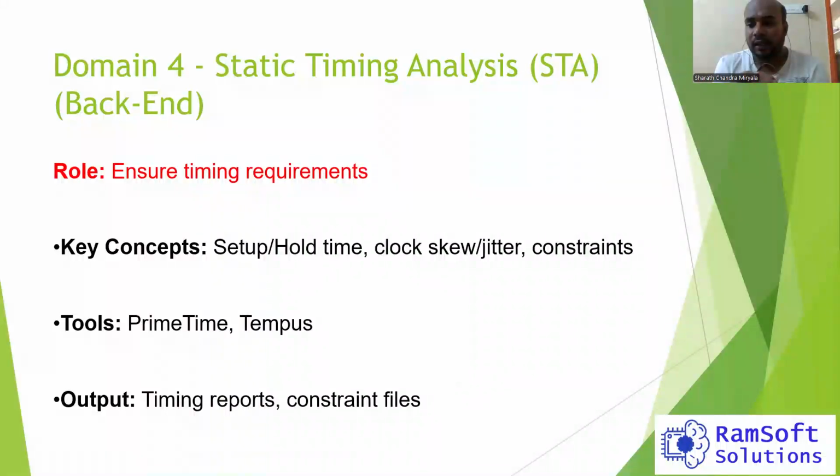You also need to address clock skew, clock jitter, and other constraints like crosstalk. The key tools we use here are PrimeTime if it is Synopsys, and Tempus if it is Cadence, to verify the timing.